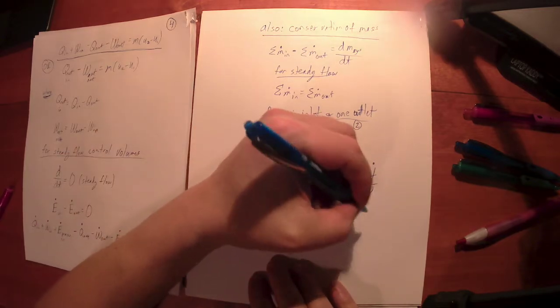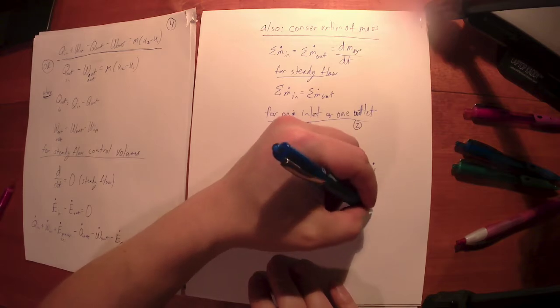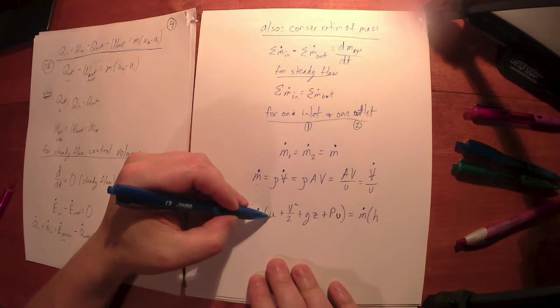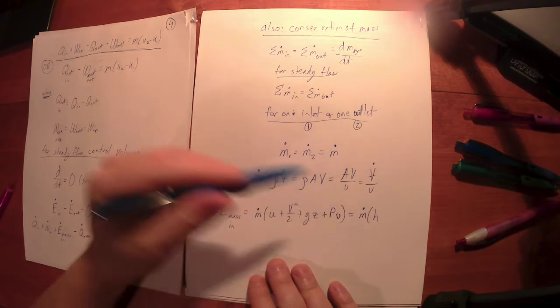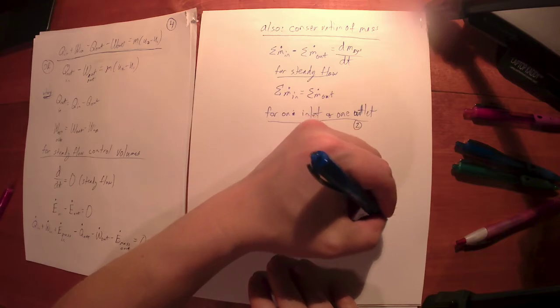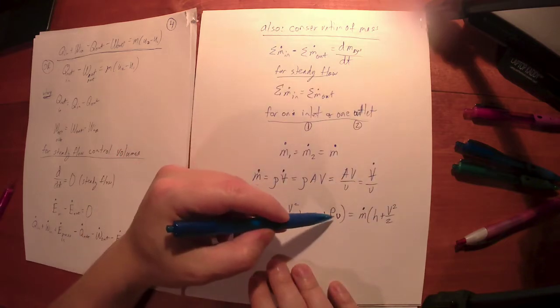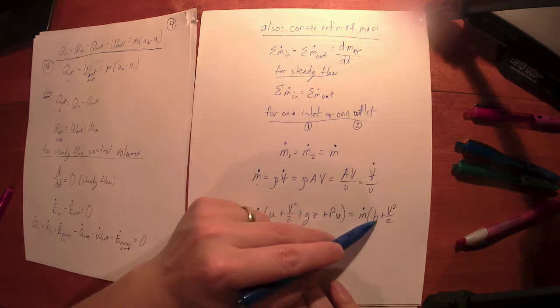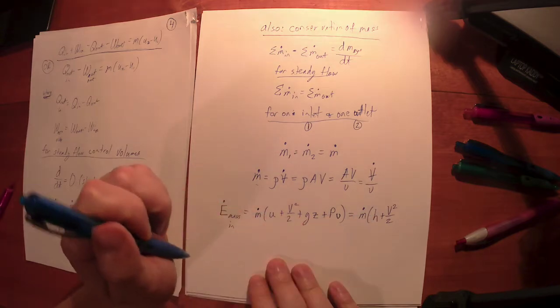But normally what we do is we use this term enthalpy. Enthalpy, the H value, is the sum of U and PV, and that's just a quantity that is defined for us. So I don't have to take the product of pressure and the specific volume and then add it to the U value. If I've got tables that have H values, and most of them do, ours do, that's already done for me.